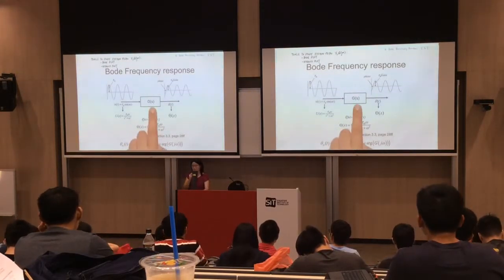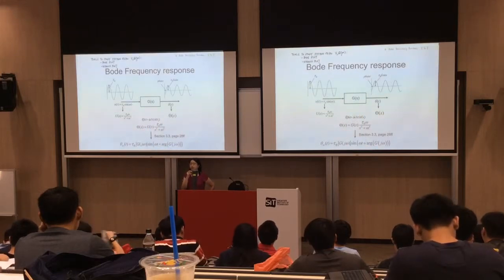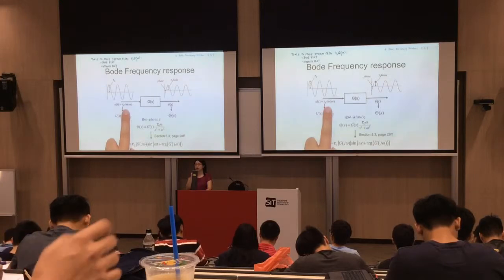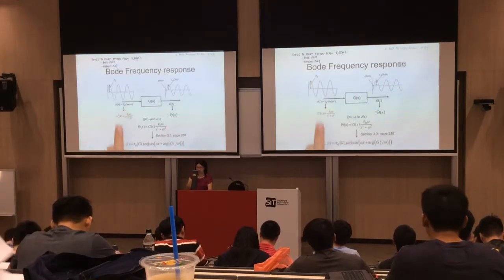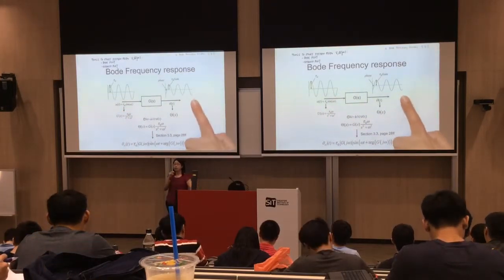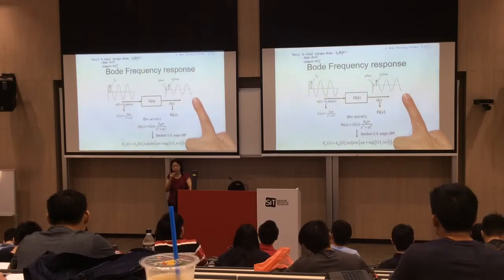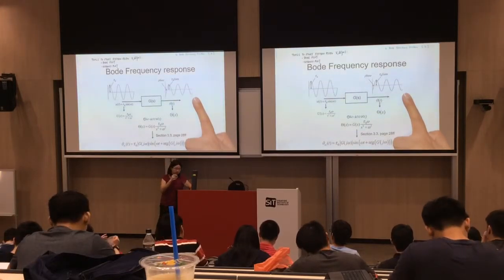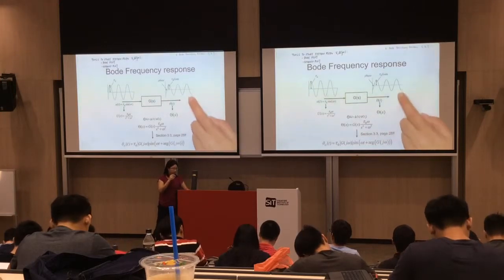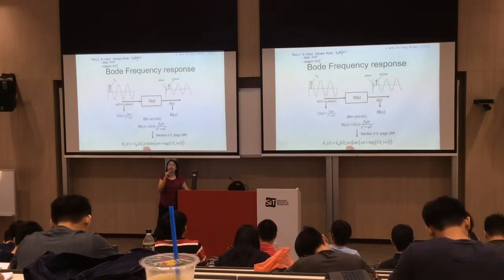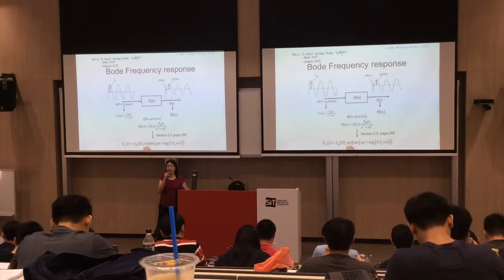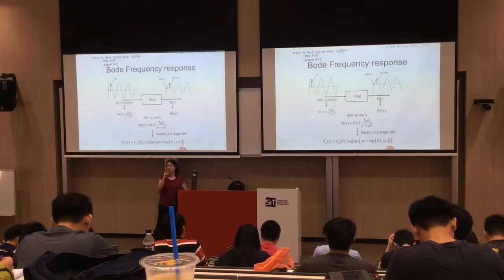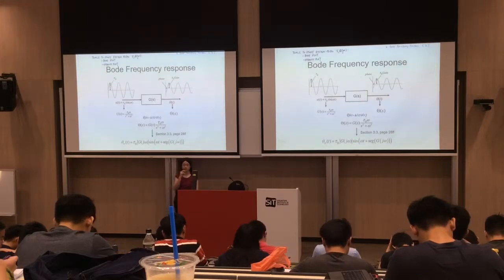So you have transfer function G(s). Alright, bounded input, bounded output. If you pass in a bounded sinusoidal input, what do I expect? Bounded sinusoidal output. Yes? What has changed? There should not be any changes except that the output will be multiplied by the gain of the transfer function and shifted by the phase. Okay, we covered this last lecture, right?